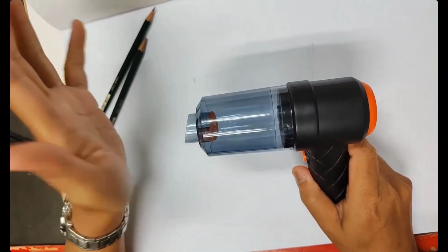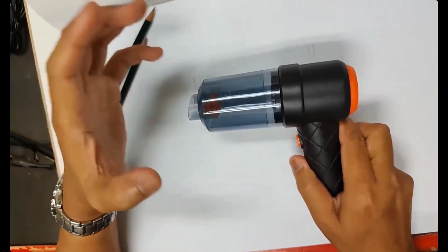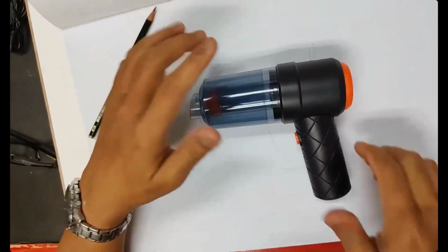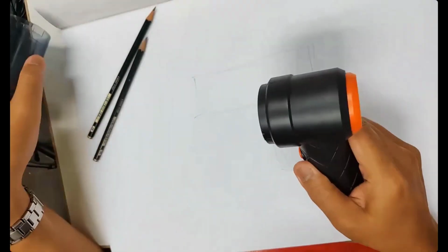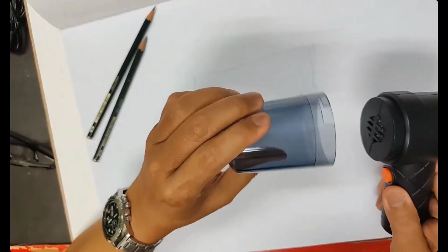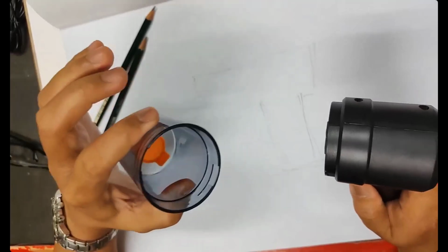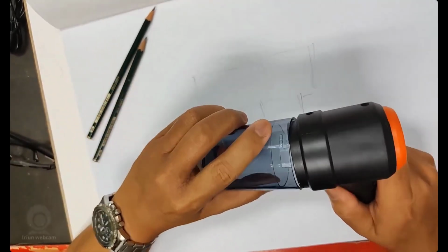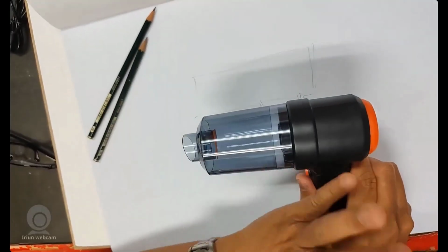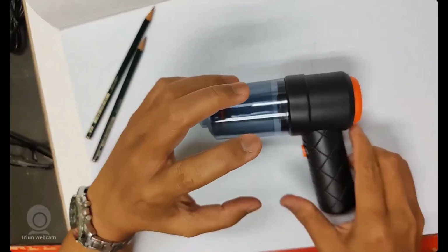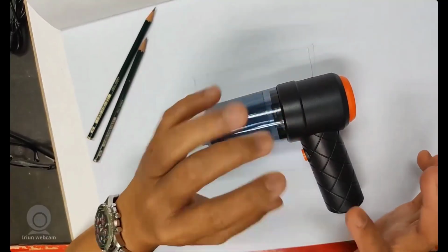For example, like in the previous video, I was doing a correction tape, or for example a protein shaker bottle. I can make it as the whole body that I will split, and I will do the main modeling. I show you a little bit, for example this unit, because this one is detached. When you do the part modeling approach, the good thing is if you make the modeling in SolidWorks as the whole body first, later you will split it part by part. That is better, because all the components before you split it kind of blend together.